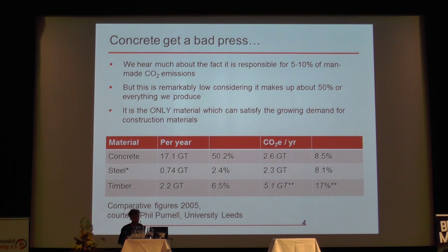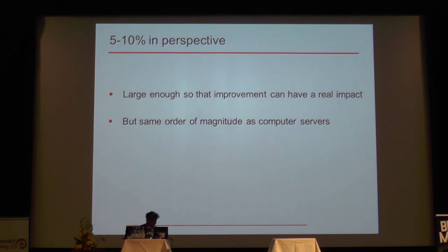The amount of timber produced is about 10% that of concrete, and even if we double the use of timber, this couldn't even fulfill the demand of increase for concrete. So it's not really a question of one or the other. It's a question that we need all these construction materials to meet demand. And concrete worldwide is going to continue to be the only material that can really be used in the quantities that is being demanded. So this 5–10%, I think we don't need to get hysterical about it either.